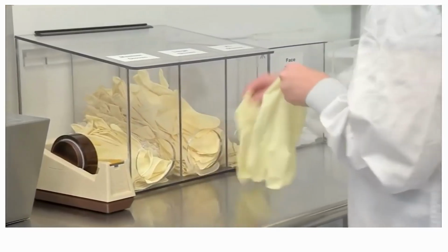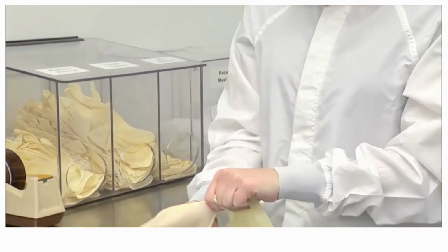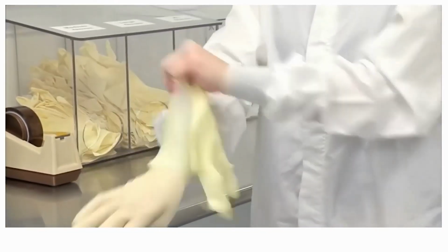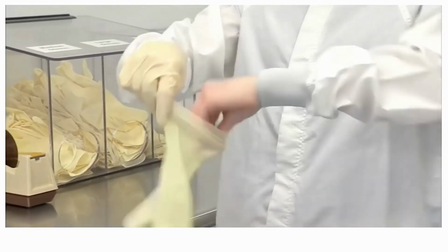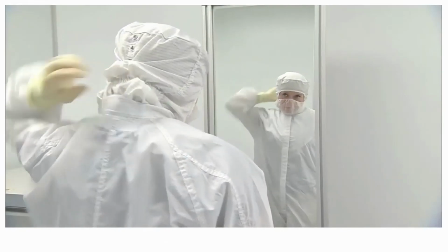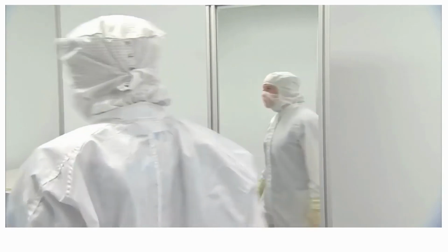Follow the same procedure for putting on cleanroom gloves, making sure to handle them by the gauntlet and avoid touching the fingers and palm region. The gauntlet of the glove will cover the cuff of the coveralls. Tape gloves as necessary for the requirements of your area. Finally, check yourself in the mirror and check your buddy if you have one. You are now prepared to enter the clean room.